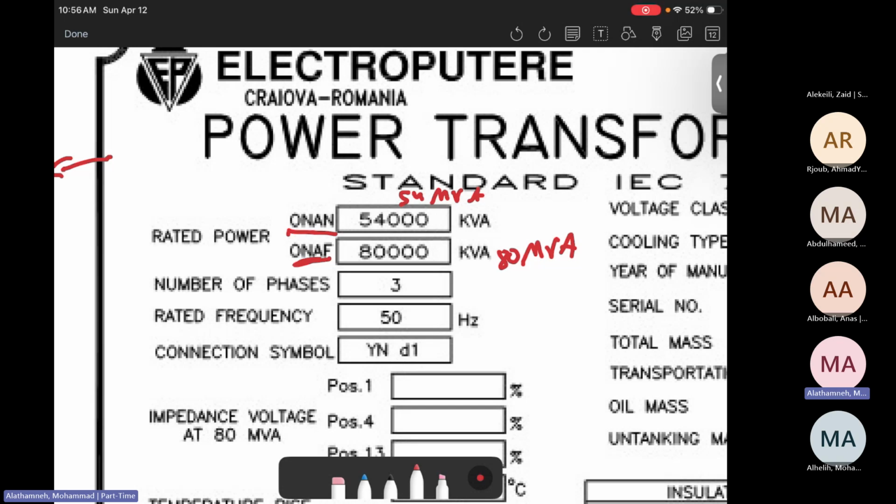The answer is, when you increase the amount of power, there will be some losses in the transformer. Those losses, eddy current losses and core losses, will be dissipated as heat. The transformer has a certain heat limit, and once we exceed that temperature, it will cause permanent damage.